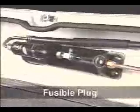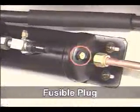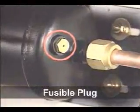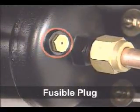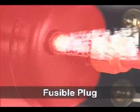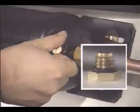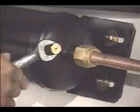A fusible plug is installed on the receiver tank. When the high pressure switch is defective and pressure increases due to an air conditioning system malfunction, there is a risk of explosion of vulnerable parts. A fusible plug melts in this case to protect the air conditioning system by discharging the refrigerant. The fusible plug is a bolt type and can be replaced by simply turning the fusible plug after removing the cause.